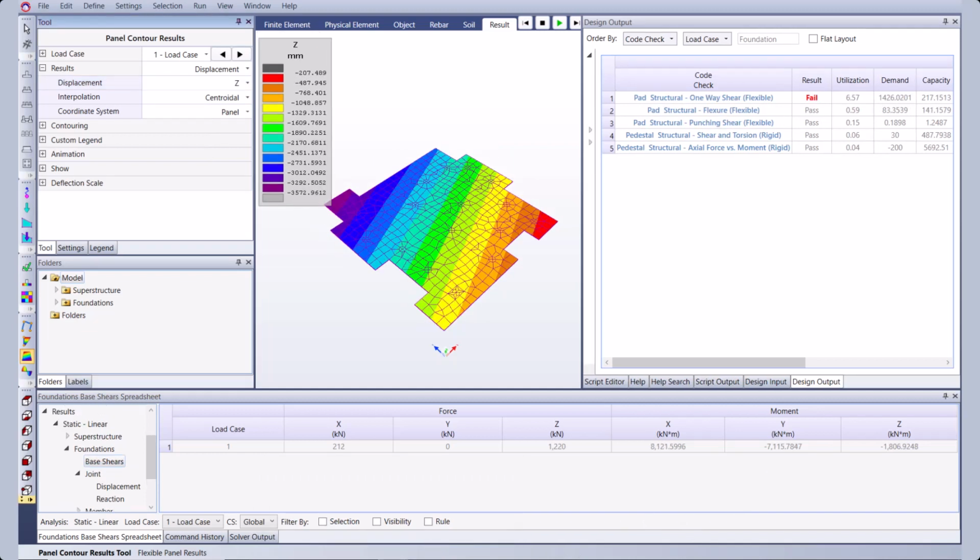So if these pile soil springs do not provide enough stiffness to the pile cap, its higher flexibility will naturally translate into the behavior we are observing. With this we hope to have given a good explanation that helps clarify how soil properties can heavily influence a foundation's demand and result in an unstable structure.